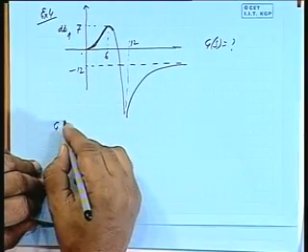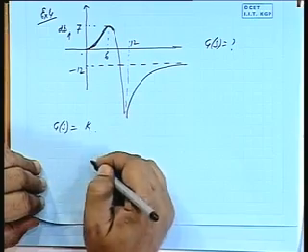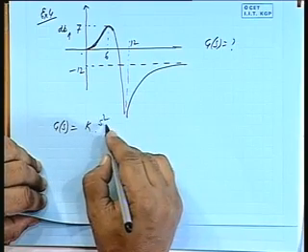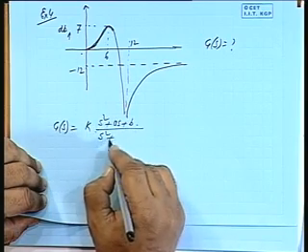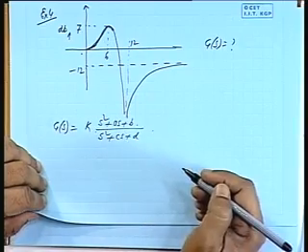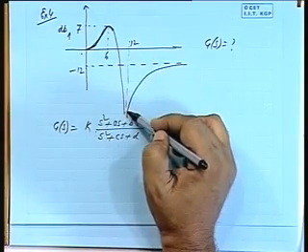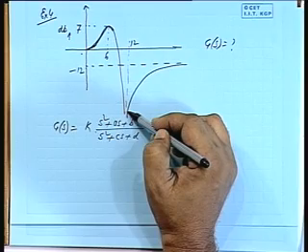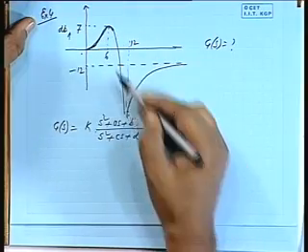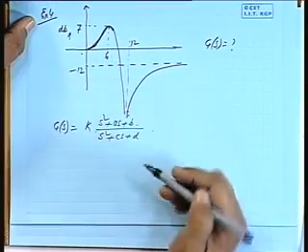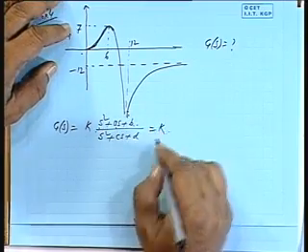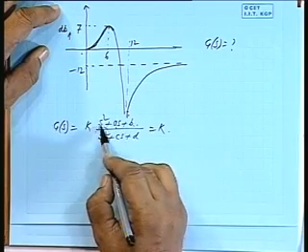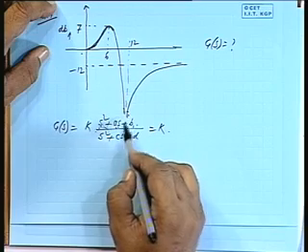So, we can write G(s) as some k times (s squared plus a s plus b) by (s squared plus c s plus d). Okay. If you remember, in the last class we were discussing omega n1 and omega n2. So similarly there are two such peaks, one in the numerator, one in the denominator. Now, tell me, in the numerator function s squared plus a s plus b, here it is tending to infinity. So how much is a?